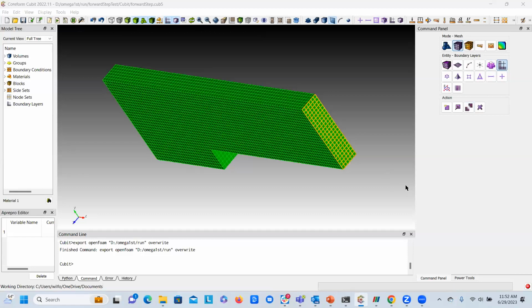And that boundary layer you are then allowed to grow from the wall that you put it in on. For example, you can tell it that I want to transition from the boundary to the main core flow, say 3 layers, 4 layers, and it will generate those layers for you. It will generate that boundary layer for you.